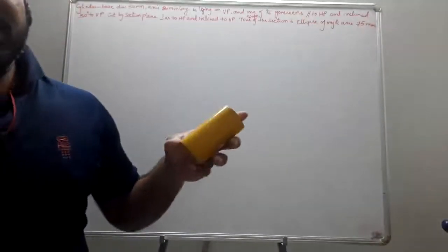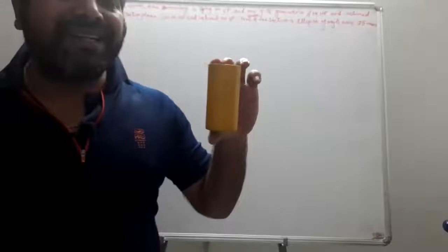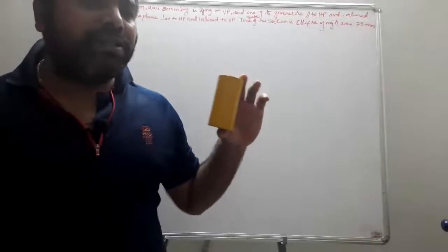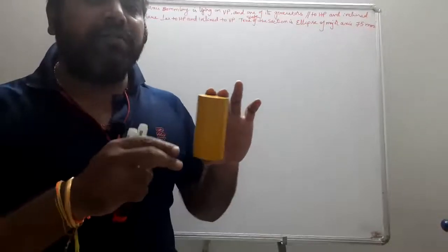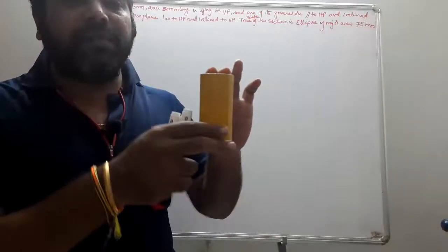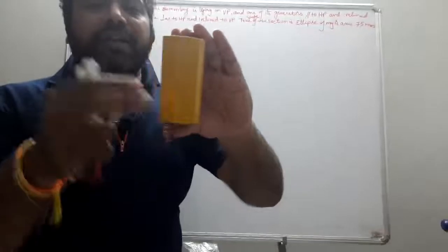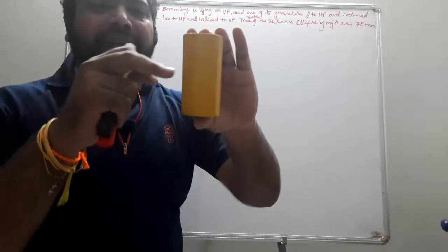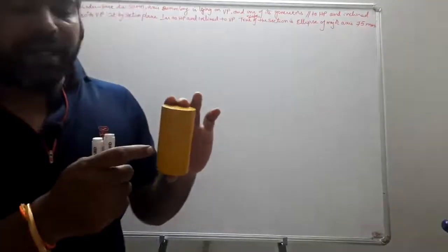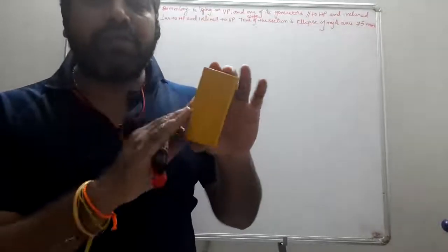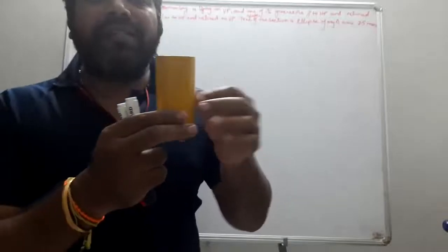What was the simple position? First of all, this was the generator. This was the cylinder having end generators. In previous problems we saw the prisms and pyramids. When your cutting plane is supposed to cut your solid, then wherever the cutting plane cuts one of the edges, you have a cutting point. But here there are no edges. This was a smooth surface having only end generators.